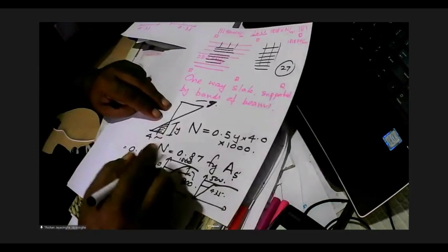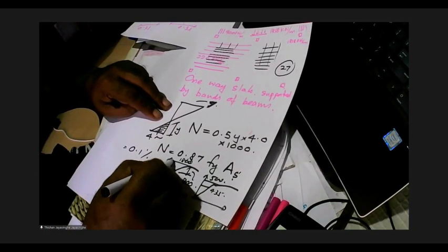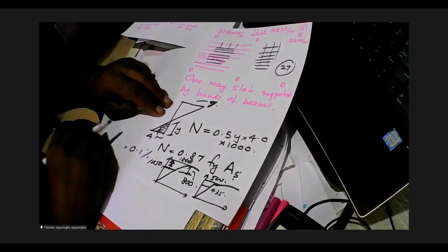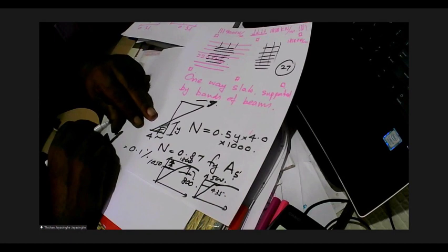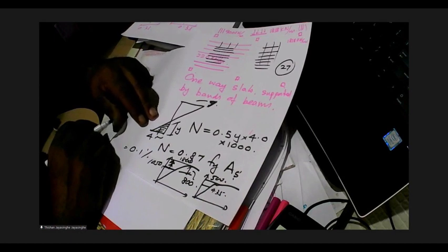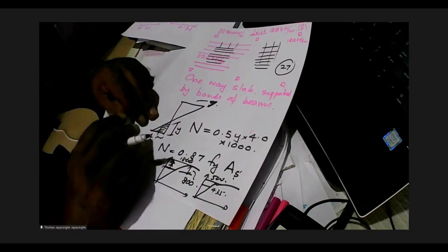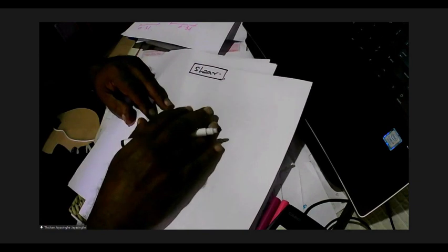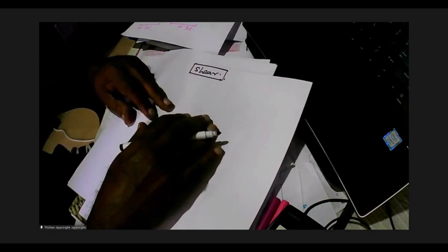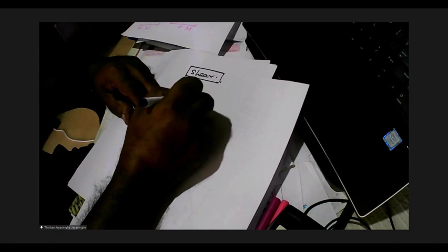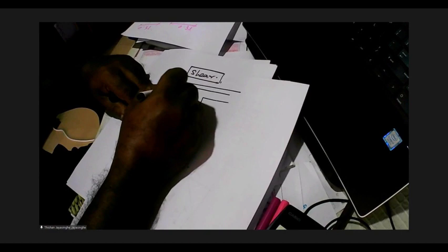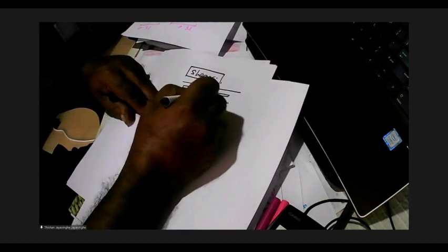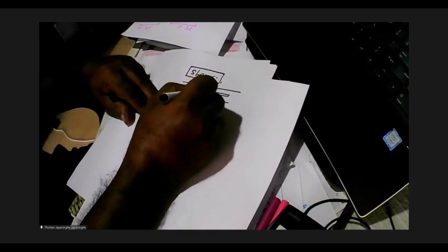What is the reason? We are here and we can go up to this level at ultimate. And then the section can crack and it can carry load at ultimate. So flexure is not a major problem. You can check and see how it behaves in ultimate capacity. But shear is a problem. So that's why in some countries, rather than using reinforcement, they put some steel sections like that. Steel. And it's called a shear head.